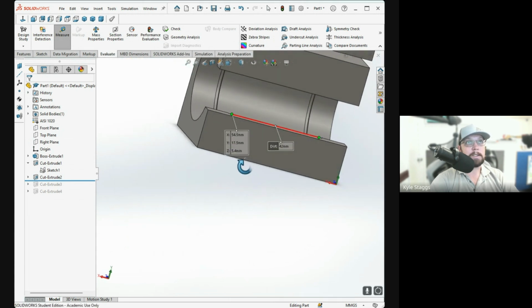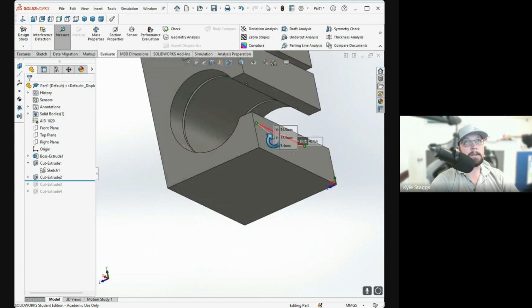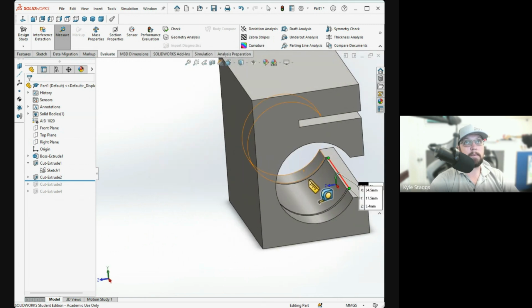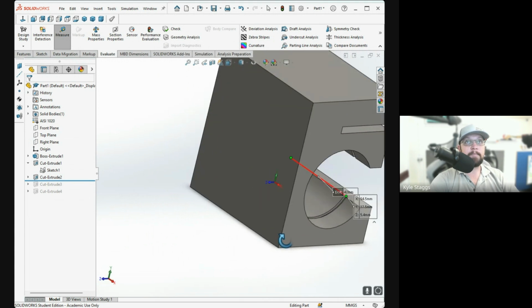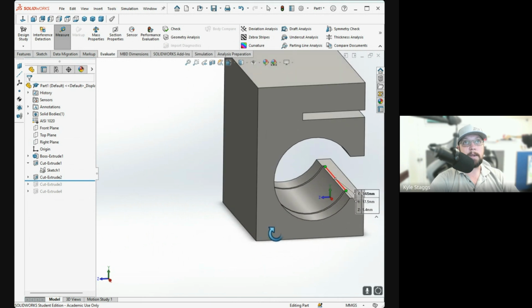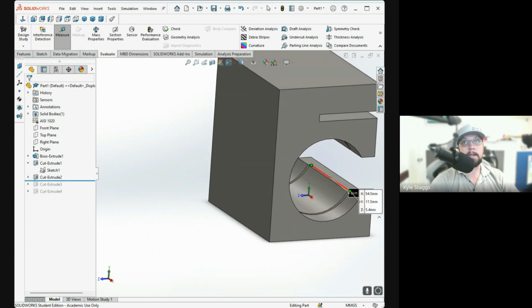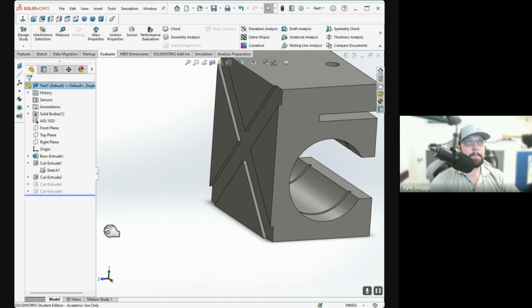That's why this is exact; this is exactly the recreation of the part. So that's 42 millimeter linear distance between the 2 insides, and that's what they mean by the 42 millimeter interior to interior spacing for the C-clip channels, the spring clip channels on that part. All right, does that help clarify how I got to here?